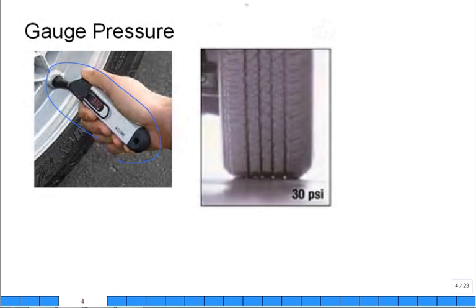Before I talk about how this device works, let's talk about the nominal pressure in most passenger vehicle tires. Most tires, you need around 28, 30 psi. True? If you have a low-profile sports car type tire, they're different. Somebody said they put in 36 psi in that tire. Anybody own one of those really low profile? What do you put in? Do you know? 32? 35, a little higher. 42.